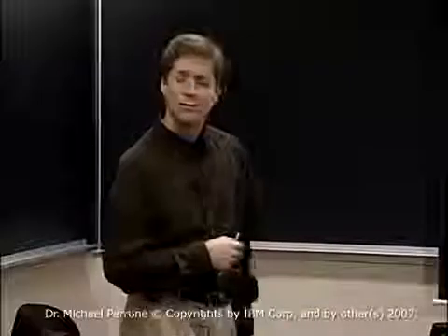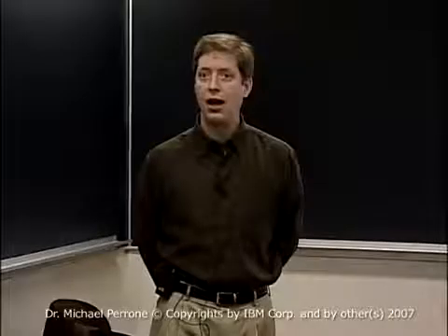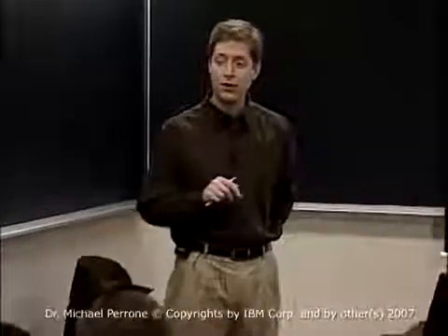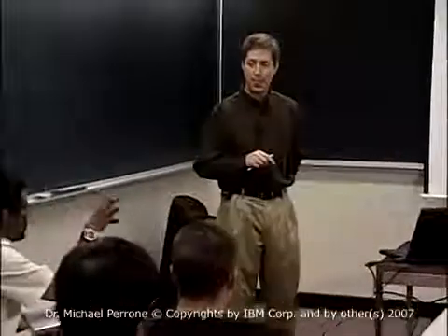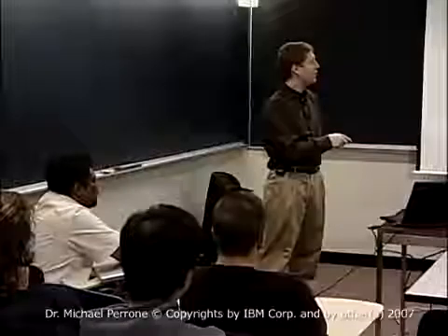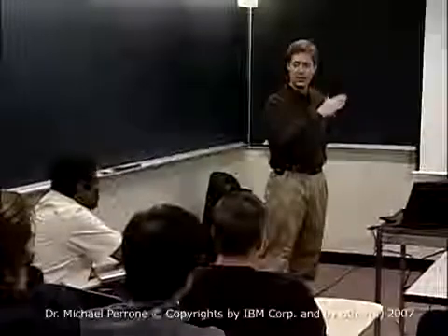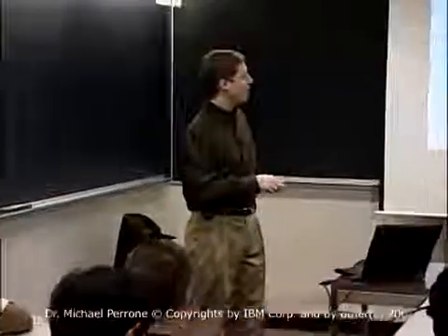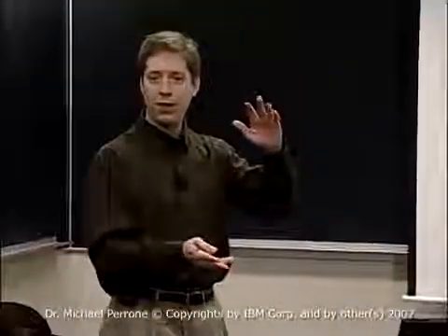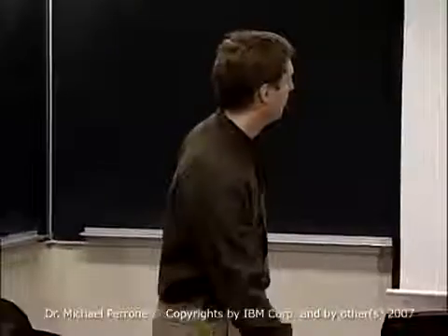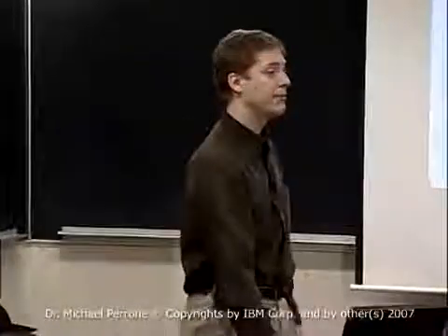So DMA engine per SPU? Yes. It's not a global one? Right, that's correct. But there is a global address space. Yeah. But 16 slots each, in each SPU. Right, exactly. Each MFC has its own 16 slots. And they all address the same memory. They can have a transparent memory space, or they can have a partitioned memory space, depending on how you set it up. Each SPU doesn't have its own.